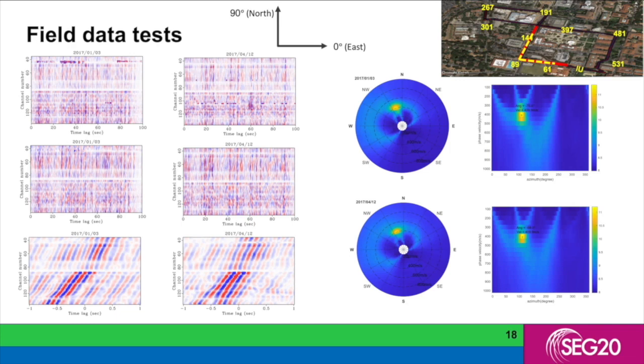The source direction can be used to correct the apparent dispersion curves. Before inverting for the subsurface velocity model, we need to identify the wave type from the data. Since there is polarity reversal in the data, it must contain Love wave. It may also contain Rayleigh wave, since there are amplitude differences between the data recorded by the two legs. But the differences may also result from the poor coupling condition.